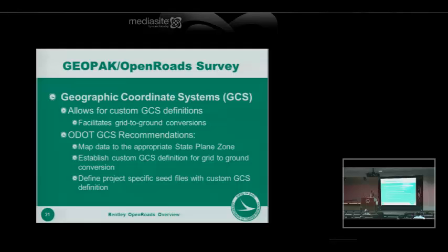I'm living in the world here. But I'm going to suggest that you want data on the state plane zone because everything you integrate with, at least I know where it's coming from. And the other thing you want is that scale factor for the grid-to-ground conversion. So you can make the custom and you can put it on whichever system you want just by picking the system.